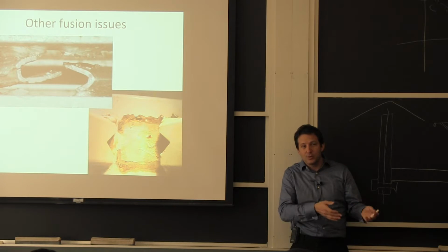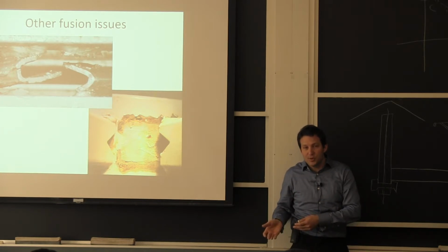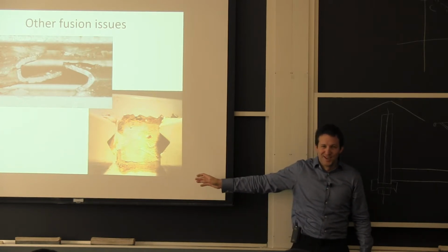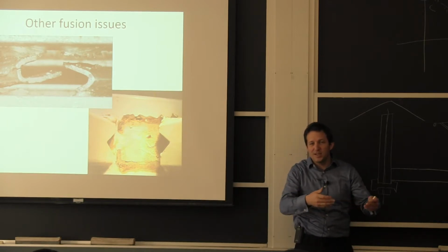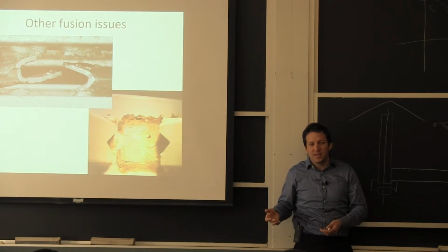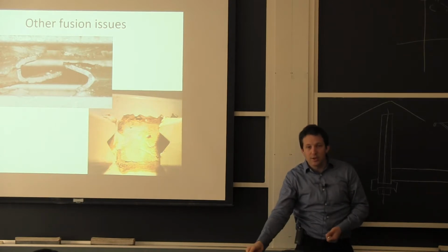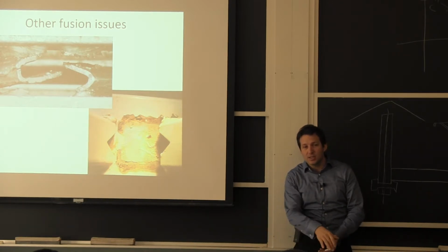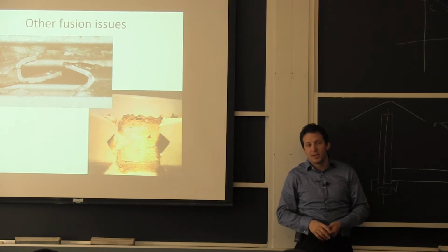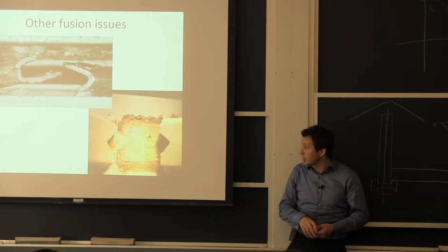You just wait for the two metals that are already there to fuse. You never have that problem, because everything needs to be really, really hot on both sides. If you go really fast, you can just caulk, essentially put metal on the surface that is not bonded because you didn't take the time to melt the base material. Yes, it's a very good question. Thank you.